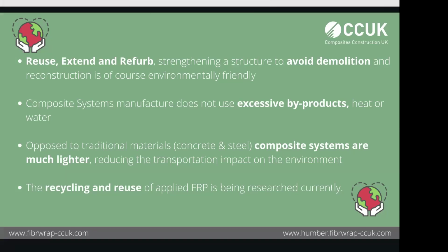Why demolish if you don't have to? You have to look at reuse or extend or refurbish the asset. When you're looking at production cost as opposed to 10, 15 years ago, it's a lot cheaper to produce carbon fiber than if you're looking at concrete or steel. When you're on a construction site in the UK, we don't need large craneage or transportation to bring our equipment and materials into site. So therefore, using carbon fiber gives you a smaller footprint, which again environmentally is critical.